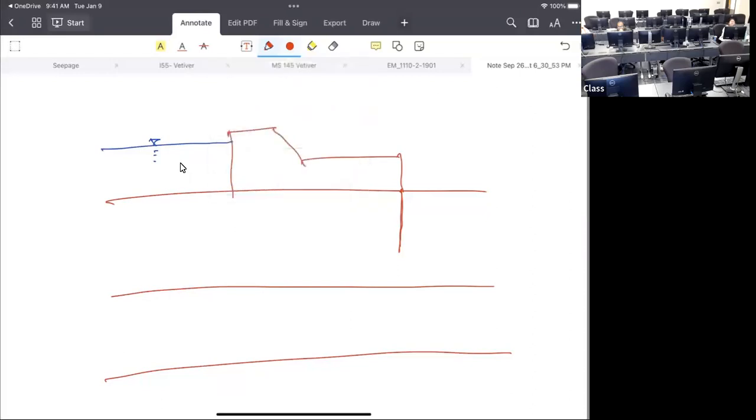Okay, so how should flow pass through the soil? It goes all the way and goes up through the first layer. I haven't applied any K1 and K2 yet, so this is your kv and kh. Usually kh is higher than kv. Here kh is twice kv. That is anisotropy.